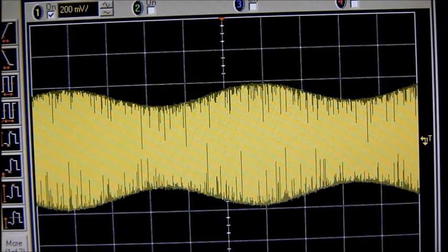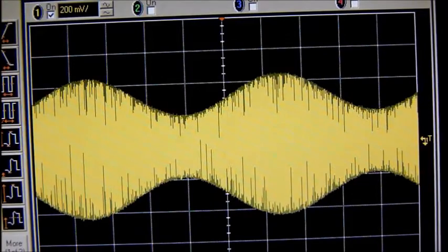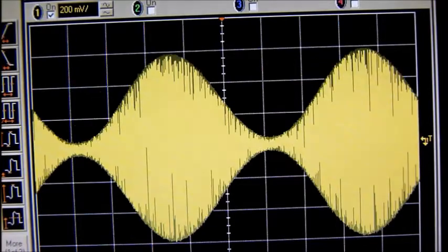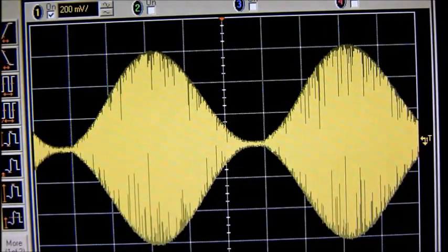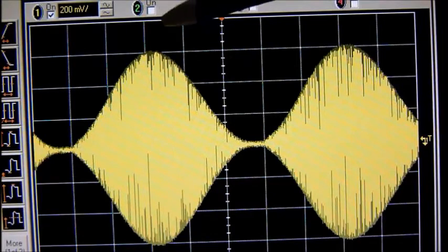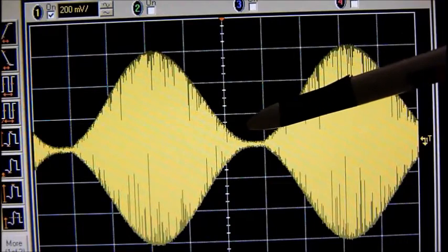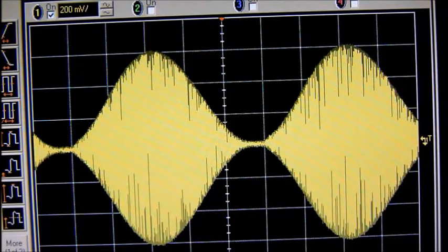On the other way, when we start increasing the modulation index, 70, 80%, 90%, up to 100%, is when the maximum difference between the envelope of the transmitted signal and the minimum of the envelope of the transmitted signal is achieved. We have to remember that for amplitude modulation double sideband large carrier, in order to employ an envelope detector receiver type, our modulation index cannot be more than 100%.